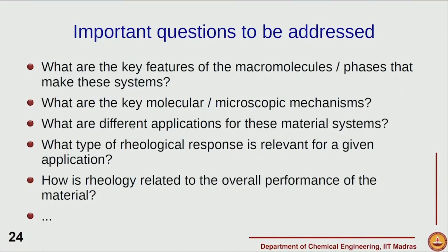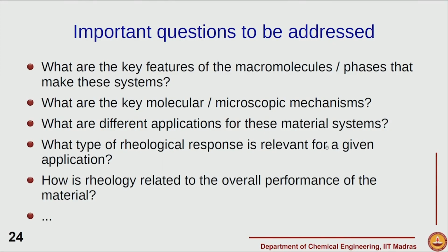And of course, we need to be very aware of what may be the applications. If it is a new material, then what is the target application? If it is a replacement material, then we know what the application is going to be like. And so, one other key question that we need to know is what type of rheological response is relevant for a given application and this material. As I have highlighted during the introductory lecture also, sometimes it is possible to look at shear flow alone, some other times we need to look at extensional flow. At some times the steady response of the material is sufficient, some other times a time dependent response of the material is required. So, therefore, what type of rheological response is relevant is a key question.